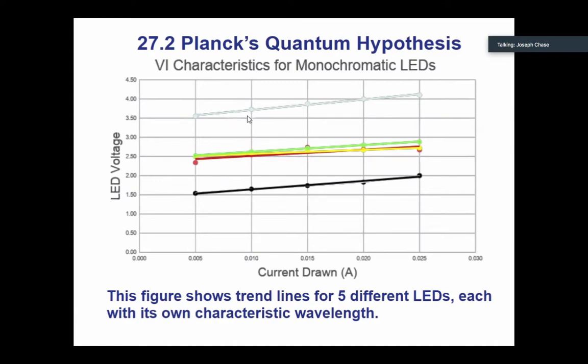If we trace this back, the threshold voltage at which an LED starts producing light depends on the wavelength. And after that, it's linear. If we know exactly what the wavelength is for each of these LEDs, and we know the threshold voltage for all these LEDs, then we could potentially see if there's a correspondence.